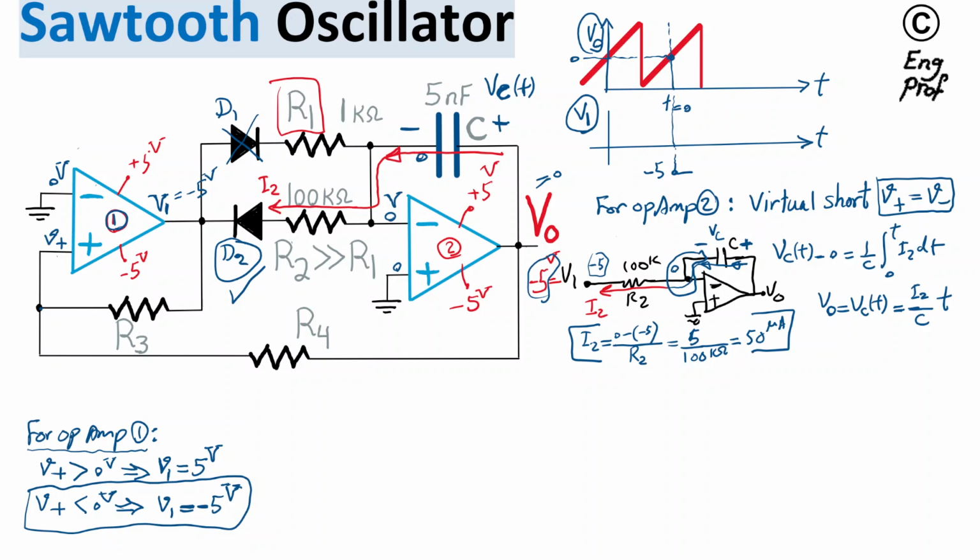So we can see that the output voltage right after the start, at time equal to T0, is linearly proportional to time. So there you go, I'm showing on top that Vout is increasing as time is increasing. And the question is, up to what point? So what is this Vmax, or Vm, at the output?